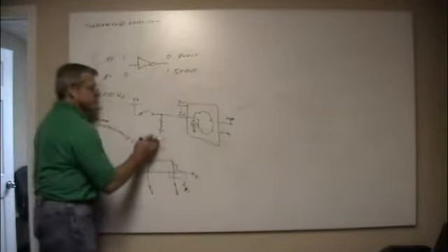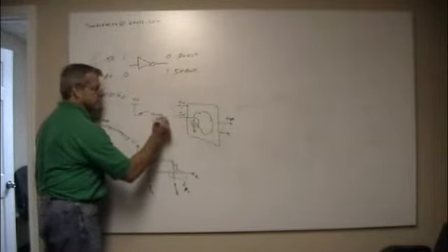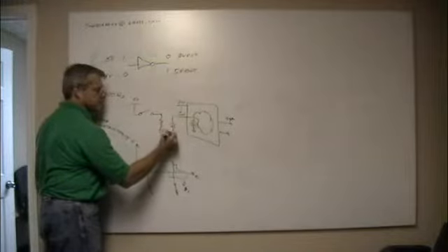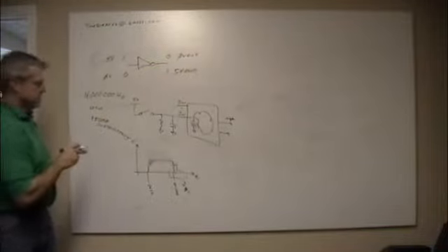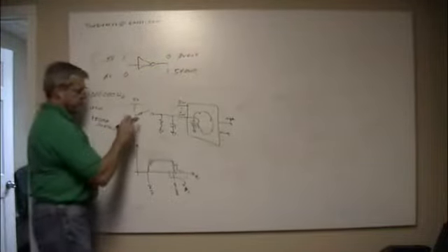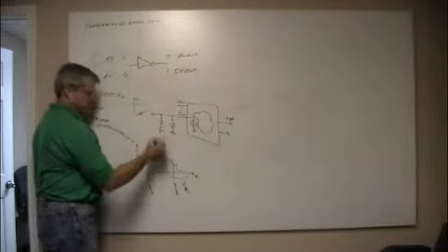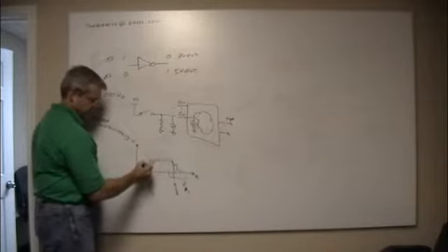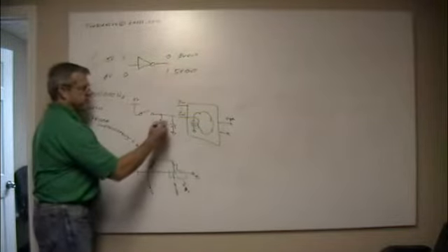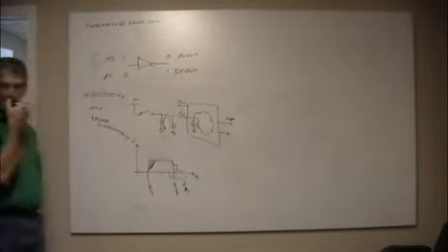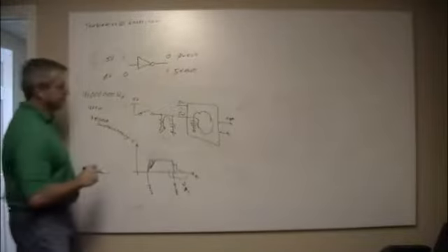Practically speaking, what you'll do is put a capacitor here. Remember, that's going to store a charge. So when I push this switch down, it's going to take a little bit. Instead of having this bounce, it's going to ramp up, and if there's any bumpity bumps in there, they're going to kind of do this. And when I let off of it, it's going to drain back out that way. That's practically how you do it.